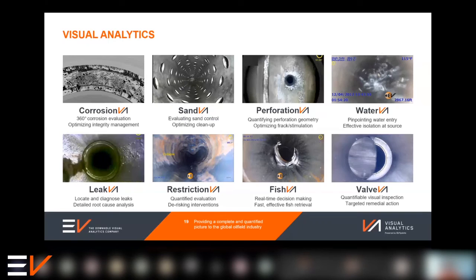We'll then come back and take a look at the success of that by placing the camera right on top of the flow tube and have the operator activate the control line. What we'll normally see is a very, very small amount of movement if the valve has been locked effectively. But if it's not, then you'll see the flow tube start to move in its normal fashion.